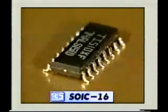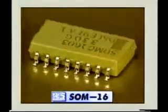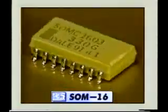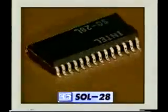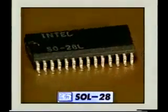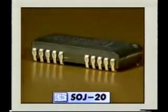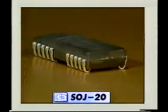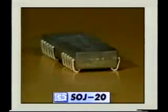The surface mount cousin of the through-hole dual inline package IC is the small outline integrated circuit, or SOIC. The SOIC has 2 rows of gull wing leads instead of through-hole leads. The SOJ, or small outline J-lead package, simply has J-leads instead of gull wing leads.